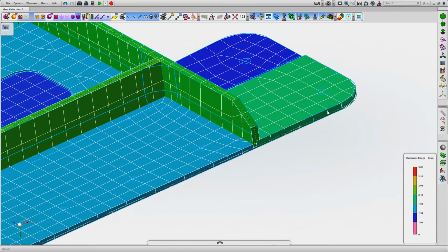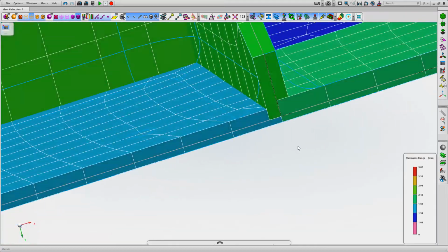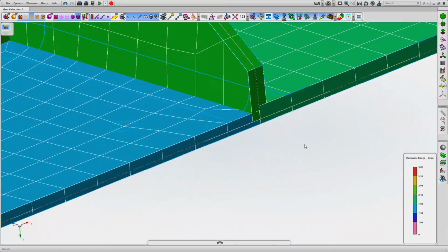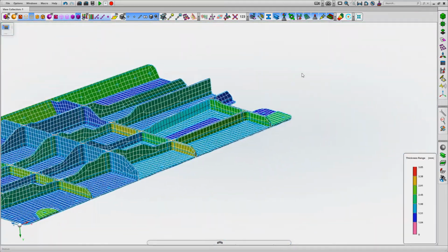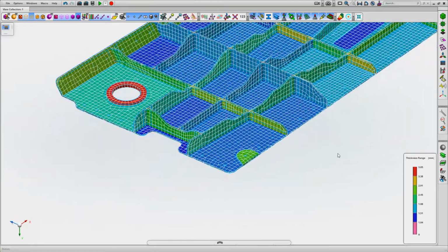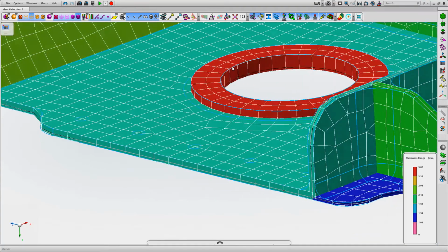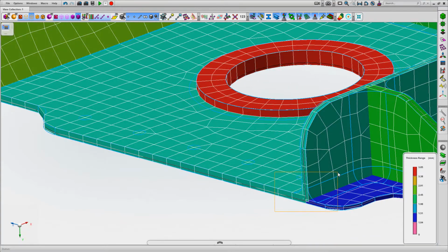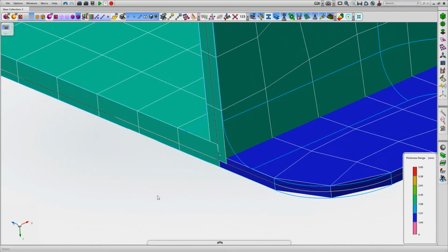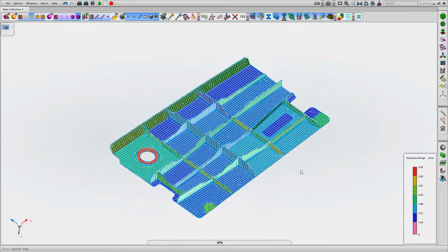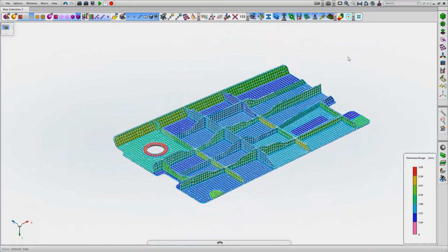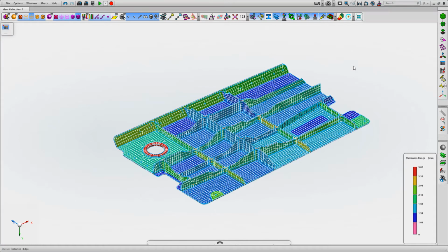There you go. So you can see the thickness ranges that have been calculated against the geometry. Okay, so we've got lots of different thicknesses in there. Okay, it's done a good job at this boss section, if you like. You can see there, again, another change in cross-section. So I've had experience of trying to do this stuff manually, and it's pretty painful, to be honest.